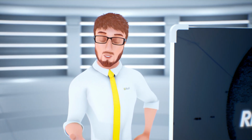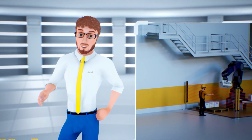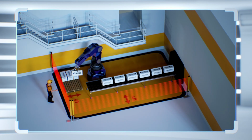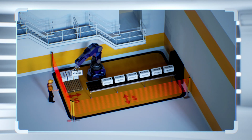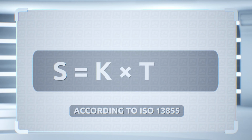Once we have decided which type of light curtain to use, the following question is: what is the correct positioning of the safety light curtain? The light curtain should be positioned at a sufficient distance from the machine hazardous point, safety distance, to ensure the machine can stop or otherwise reach safe condition before any part of an approaching operator can reach the hazardous zone. The formula for calculating the safety distance is S equals K multiplied by T plus C.